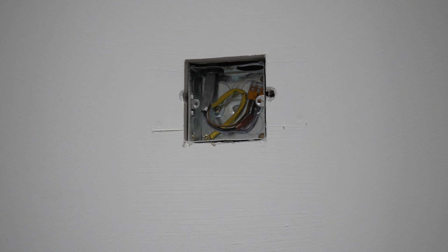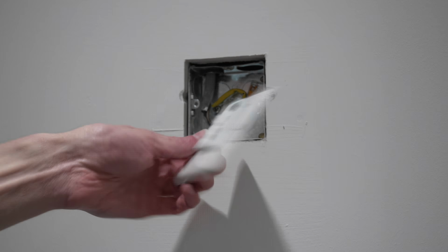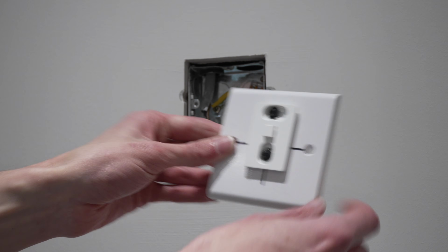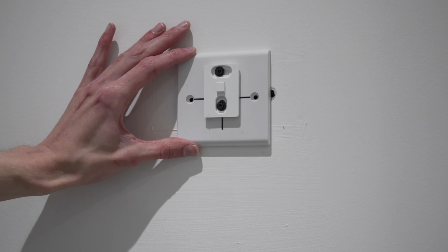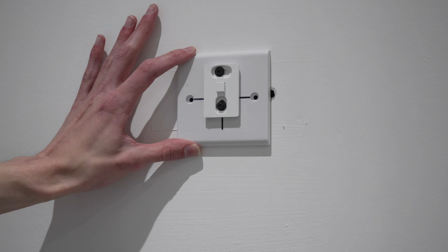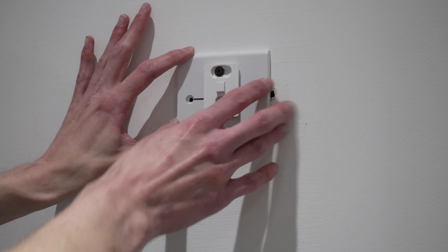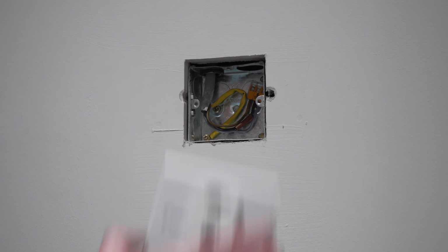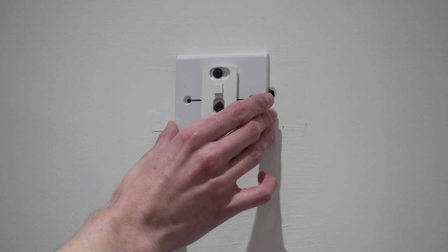But instead what I've done is this. All I've done is I've taken a blanking plate, drilled a couple of holes in it, and fastened the Wiser bracket, the mounting plate for the thermostat, onto the blanking plate. So what I can do is screw this over that existing back box, and then just clip the Wiser thermostat onto that, and it'll make it look a bit less like a blanking plate because there'll be something actually useful there, and it means the thermostat's then mounted. There's a little bit of filling I'll need to do here and here. That's for the old thermostat that used to be here before the Tado. It was screwed in there and it's a little bit of a gap, but that won't be too hard to fix. So I'll get that on the wall and we get the thermostat mounted.